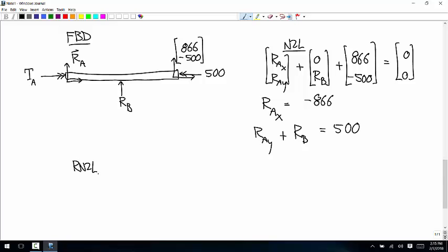And then the moment equation. Well, we have to decide which axis we're going to do. I guess I'll do X first. For the moments about the X-axis, it doesn't matter what I choose as the about point because the only things producing moments about the X-axis are couples.